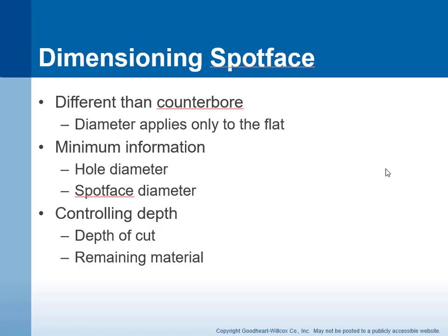Okay, we're still talking about dimensioning features. Let's talk about spot face now. A spot face is a little bit different than a counterbore. When you're dimensioning a spot face, the diameter only applies to the flat surface. Okay, so that would be just a flat surface, doesn't include the radius. The minimum information would be the hole diameter and the spot face diameter.